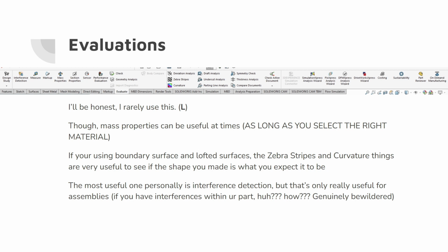Okay. So I want to find the distance between, let's say, this point and this point, right? Normally, if you're in an assembly and this is the part, you will have to put a sketch on the screen and then pull a line over here and then measure its distance. But what I can do is, even if I don't have the measuring tool open, I select this point, control select this point, press the measuring tool button. It automatically tells you how long it is.